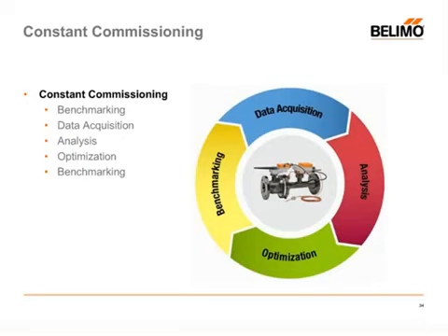This is where you would be running the energy valve in one of those modes of control, where say it's just a pure pressure independent mode. Then you would use our data analysis tools, such that you could actually do a best fit for the energy curve and the delta T that the air handler is actually experiencing, and then do the data manipulation, where it would actually select.